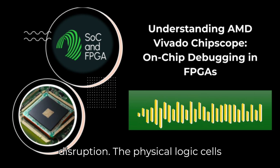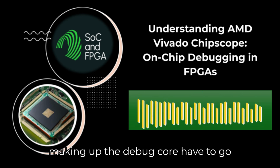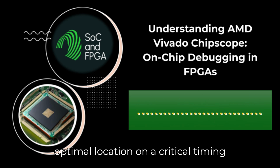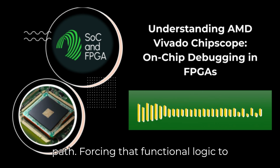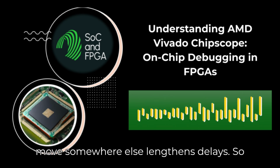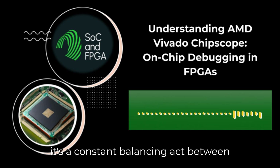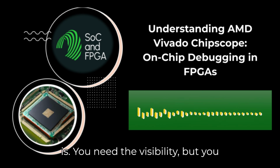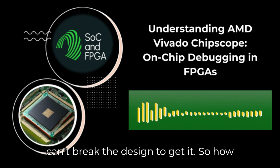The physical logic cells making up the debug core have to go somewhere. Sometimes they displace functional logic that was sitting in an optimal location on a critical timing path. Forcing that functional logic to move somewhere else lengthens delays. So it's a constant balancing act between visibility and performance. It absolutely is. You need the visibility, but you can't break the design to get it.